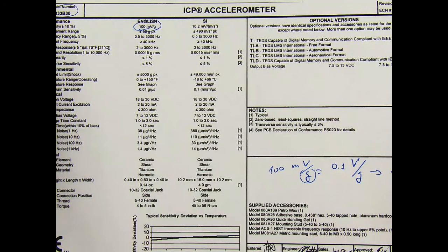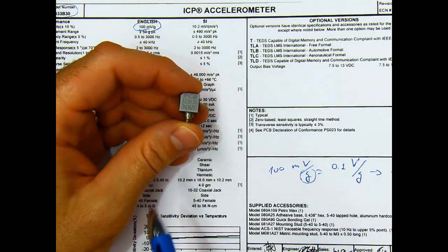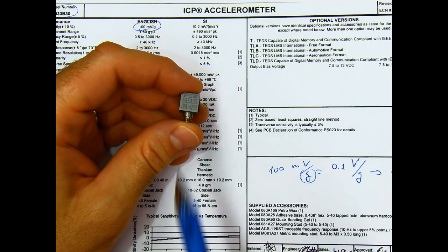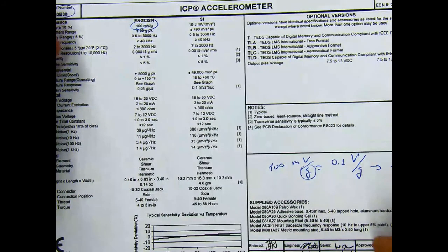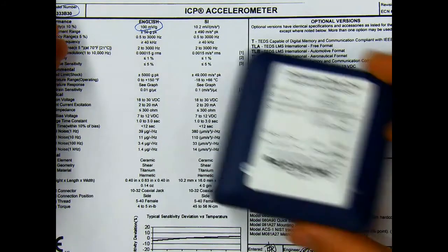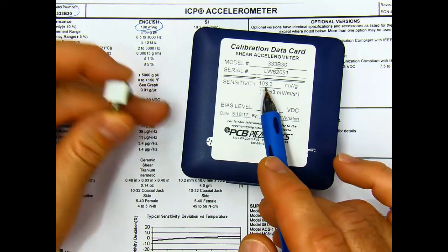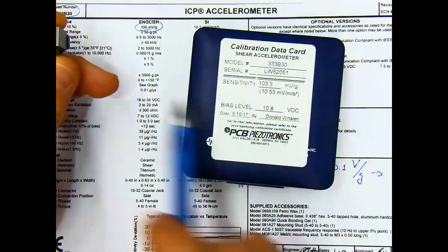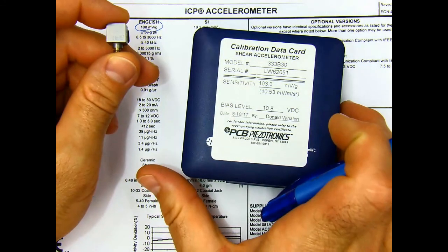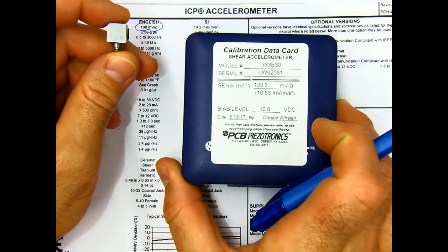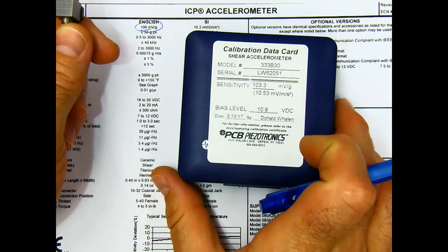A quick side note before we continue. High quality lab equipment like this sensor, they all have individual serial numbers, and they are calibrated individually at the factory. So as a consequence, each sensor will have a slightly different sensitivity value than the datasheet value. So it depends on how precise you want to be with your setup. You can use either this or this. The choice is yours.